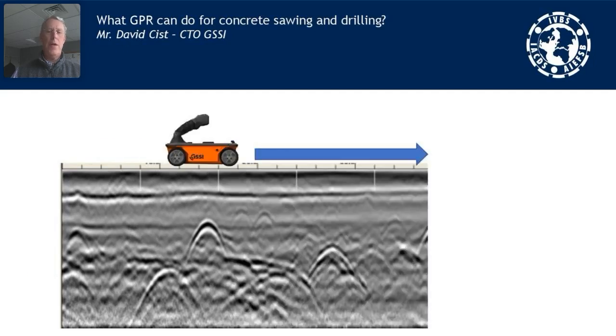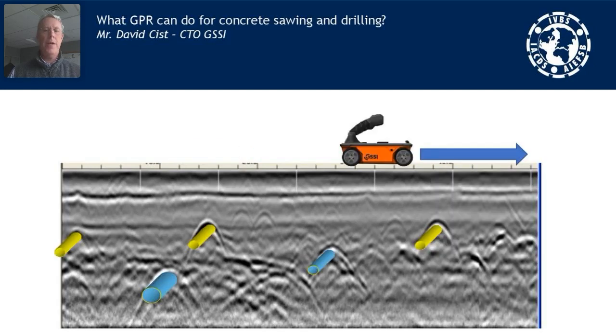As you move the radar over the surface, you see a scan developing where you can see fairly complicated patterns, but typically the targets show up very clearly and you can map them and know where they are. In this case, for example, these are some rebar targets and 2 PVC pipes, and you can see them very clearly in the signal.